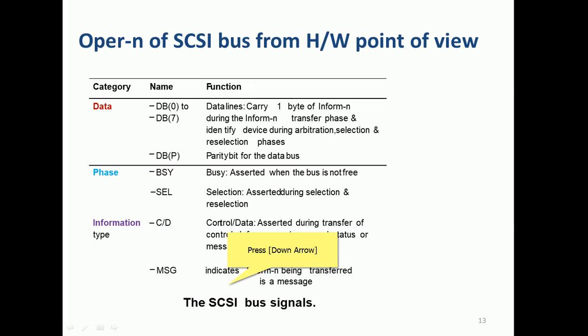On completion, as we discussed, the target controller, that is the SCSI controller, informs the processor after completion of all the data transfer from the identified sector on the disk. Like that, an end message and a start message are needed. So the messages are sent in order to have proper communication.